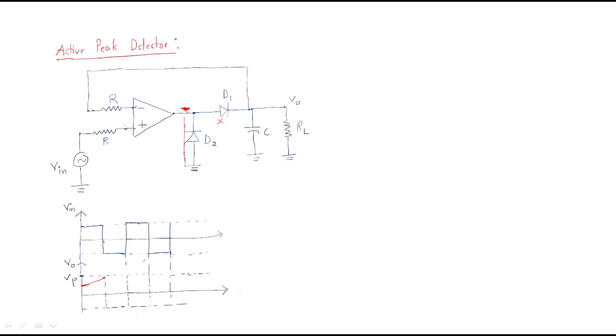Then the total current will flow like this, and the capacitor itself has the voltage and doesn't have any path because the resistor value is high. Here the resistor is very high, acting as a buffer circuit. So there is no path for the capacitor. The capacitor value is almost fixed, and may slightly decrease. After a positive voltage it will again increase, and with a negative voltage it again decreases. So these values are the peak values, the maximum values.